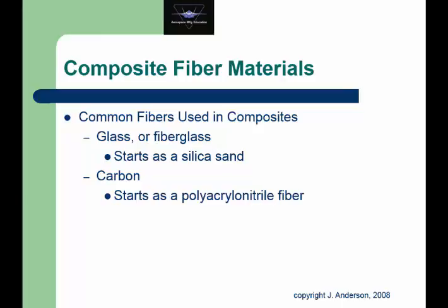Aramid materials are cousins to nylon. They're a polymer material. The name comes from the fact that the molecular chain, which is the backbone of this polymer, contains both amide and aromatic groups. Because it contains both of those, and because of the mechanisms of entangling those molecular chains, you end up with an overall material that has a fairly high tensile strength and a fairly high melt point.